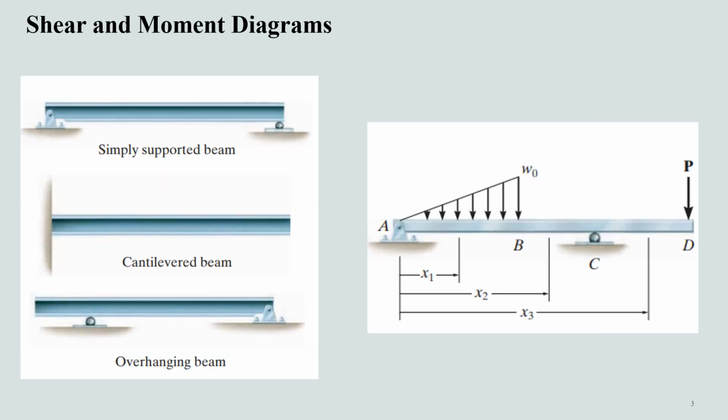Okay, so bending is the main concern in beams. So mostly when we are discussing bending, we are focused on the structural elements that act as beams. Members that are slender and support loadings that are applied perpendicular to their longitudinal axis are called beams. In general, beams are long, straight bars having constant cross-sectional area. Often they are classified as how they are supported.